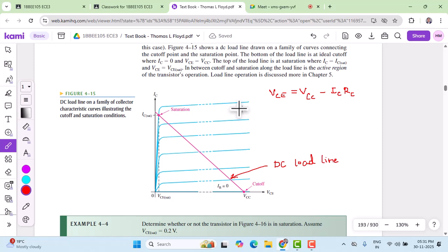Okay. If we cross this equation, if you have a question like what happens if I cross these points C and D, you are violating this 500 milliwatt, and that leads to unsafe operation of the BJT. So the product of 10 volts and 50 milliampere gives me 500 milliwatt. The product of 15 volts and 33 milliampere gives me 500 milliwatt. The product of 20 volts and 25 milliampere gives me 500 milliwatt. In that context, we are not exceeding the maximum power defined by the manufacturer.